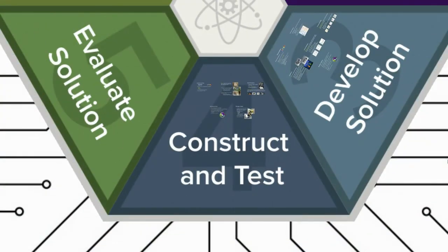It would be miraculous if a design team reached the end of step 4 without the need for major revisions. That's how the design process works. If the first model indicates a flaw in the design, return to an earlier step, correct the issue, and then move forward again. If the initial prototype has trouble during testing, diagnose the problem, return to an earlier step, and make some changes. Designers will often cycle through steps 3 and 4 many times, making many iterations of a design before they make a fully successful prototype.